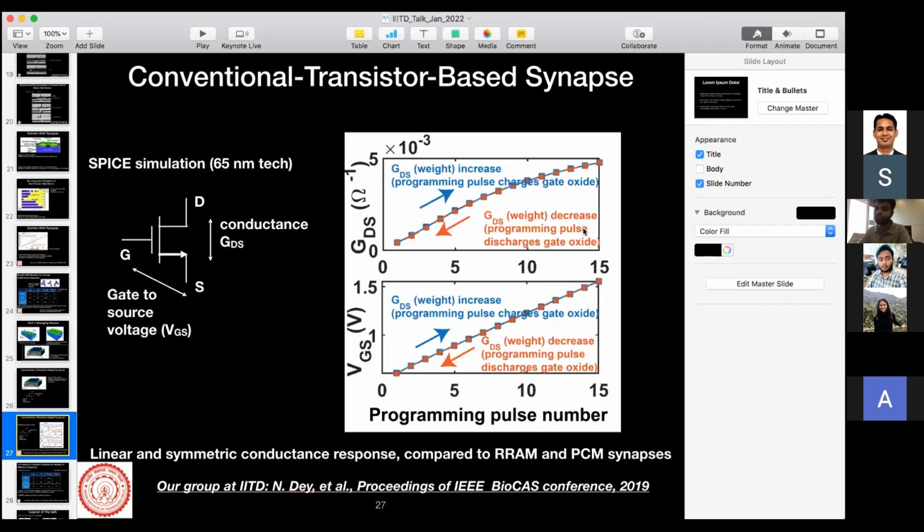But there are other groups who are working on it, so you can look up those papers. They're called DRAM cell papers, right? DRAM-based crossbar arrays of neural networks for training neural networks and all that. So that will work, but because we are trying to store multiple bits, like 5 or 6 bits, in one synapse transistor, this idea doesn't really work well. Makes sense? No, that's a good insight.